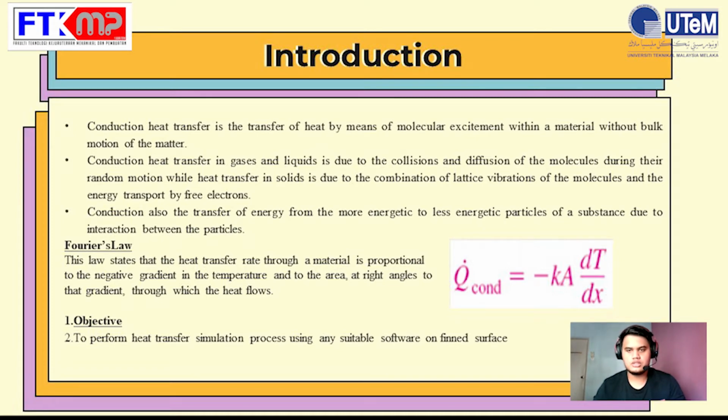Conduction heat transfer in gases and liquids is due to the collision and diffusion of the molecules during their random motion, while heat transfer in solids is due to the combination of lattice vibration of the molecules and the energy transport by free electrons. Conduction is also the transfer of energy from the more energetic to the less energetic particles of a substance due to interaction between the particles.